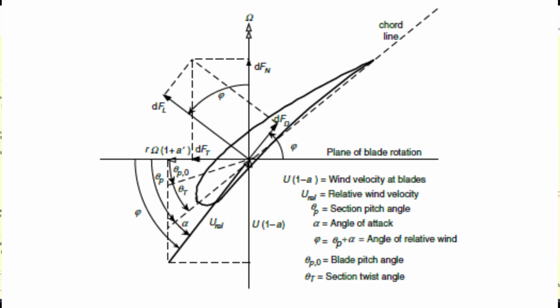So once you have the twist as well as the chord width, you are then able to optimize the wind turbine blade for aerodynamics, which is method 2, where estimated geometry parameters are already known. However, optimization of this geometry is performed when you're able to get the induction, you're able to iterate over and get new values of induction as well as angular induction values.